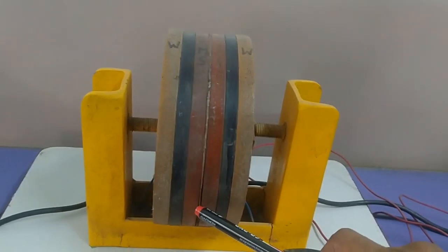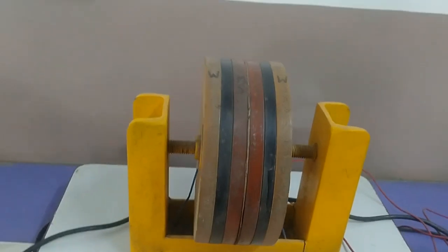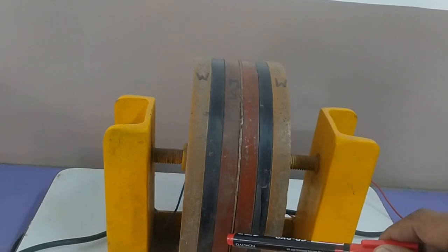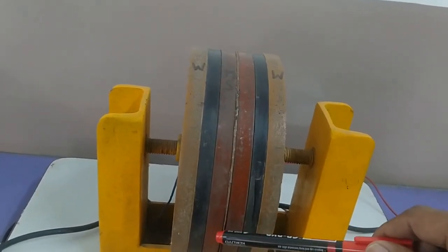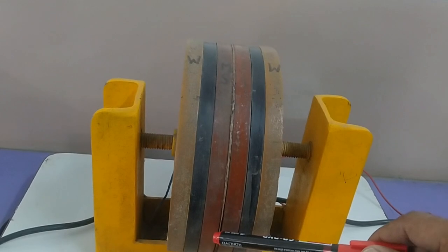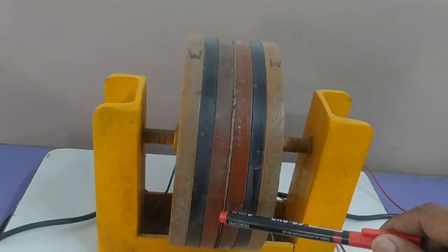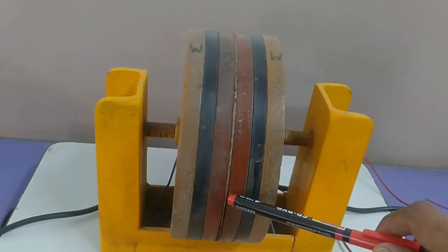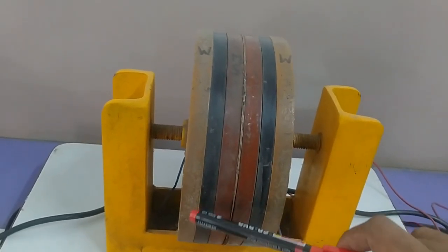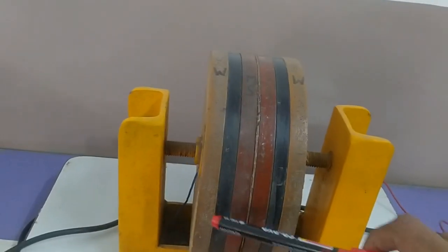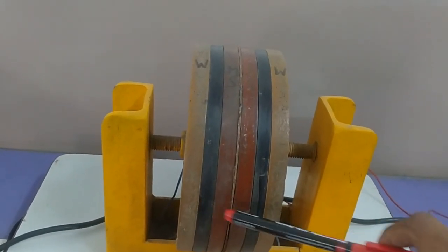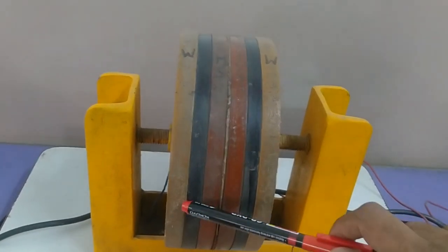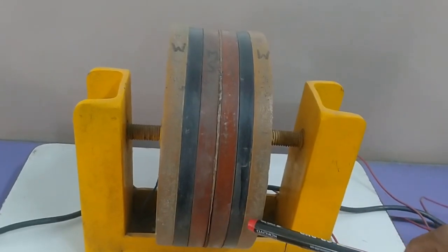So to reduce this loss we have arranged this setup in such a manner that the heat produced by the heater will pass through both sides equally. If heat is passing from the heater to the outer side equally, we have to arrange the mild steel, then bakelite and wood symmetrically. So this is a symmetrical arrangement of mild steel, bakelite and wood. Heat is flowing through the mild steel equally, similarly the bakelite equally, and the wood also.